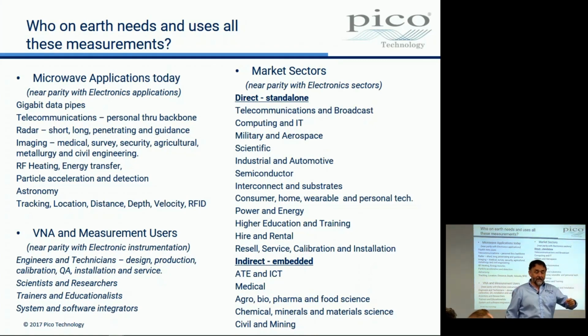What does it do? It takes an electromagnetic wave from a piece of cable, and if you make your antenna correctly, you're going to inject that into the ether. You're going to match it to the ether. Yeah? And if the antenna were not correctly matched, you get the signal back instead of it going to the ether. So it's another DUT for a VNA. You're quite right. Yeah.